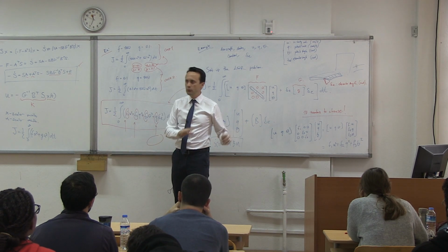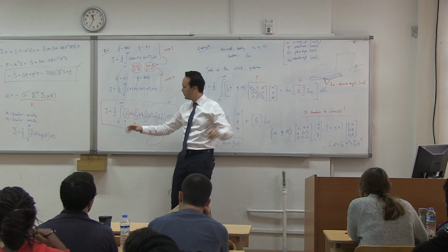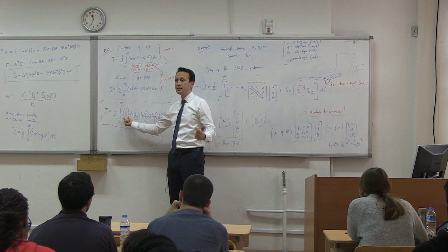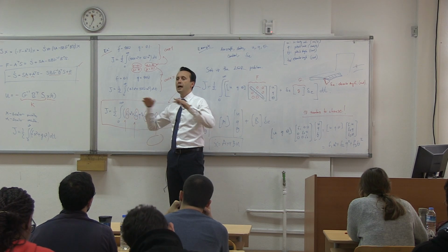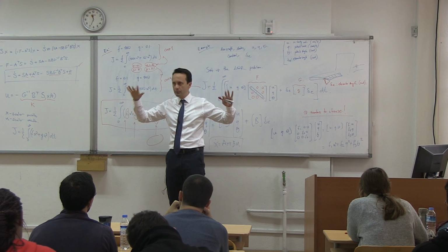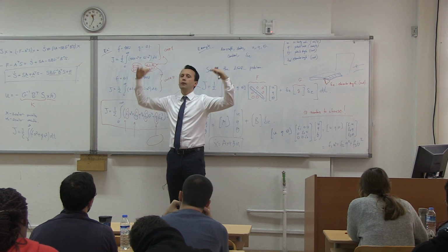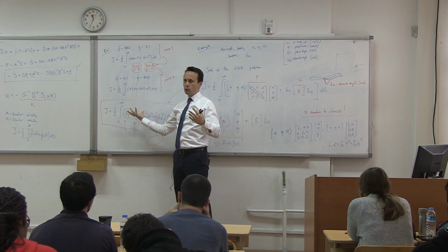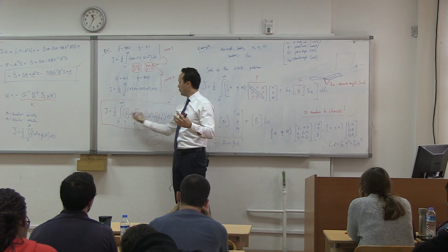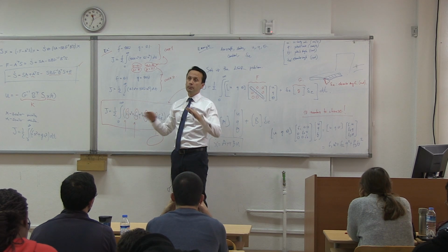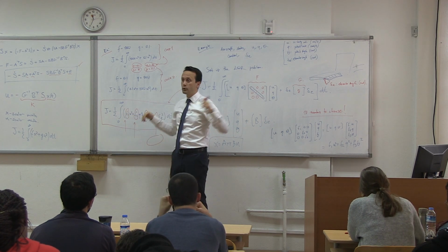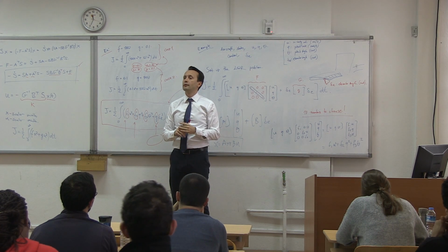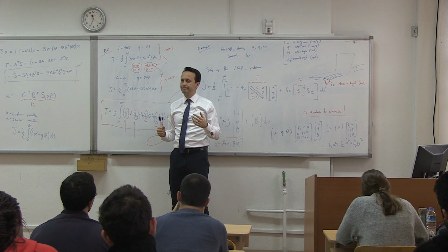So the first thing you need to do is put everybody into the same level, meaning that first put F1 small and these ones large, since these are radian and this is meter per second. And after you put everyone onto the same level, approximately, then you can go ahead and say, let's make Q more important, then you slowly increase Q, or slowly increase the control, or slowly increase U. But first put everyone onto the same level in terms of the units, because this is a dull optimization problem.